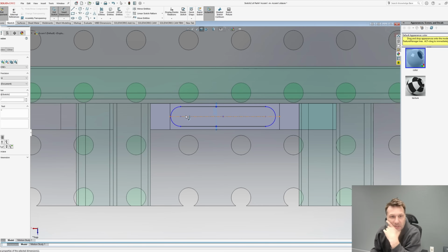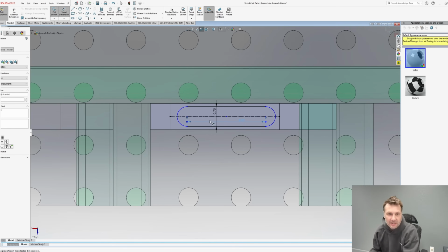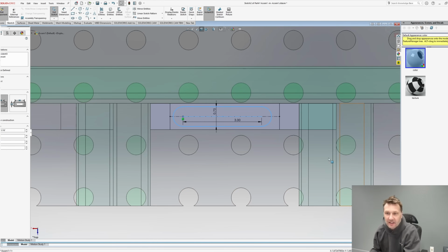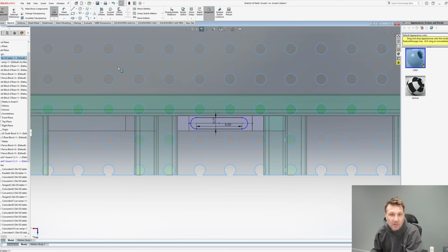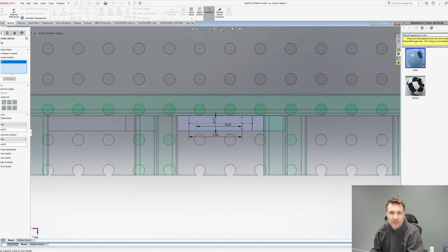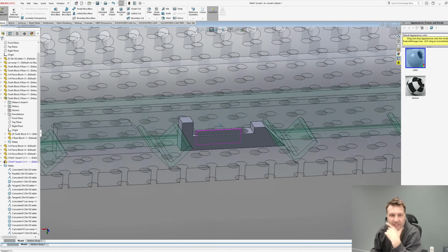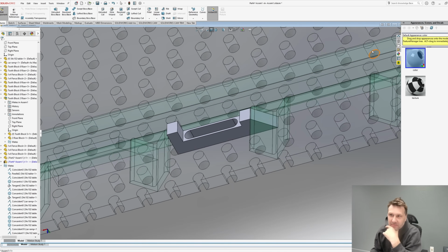If we don't want this to be too big, let's just make this 3 inches. Technically it should be 4. I don't really know where it's going because this could be varying as we jump this. See how the slot's going to change. As long as we can get one hole to hold it down, I think that's really all I'm looking for. And then I'm just going to fully define this sketch. Hit OK. I'm going to extrude cut 1 inch. And there we go. Okay, so I have this kind of funky, weird fixture that we just made. Kind of fun, right? And I'm gonna hit OK.